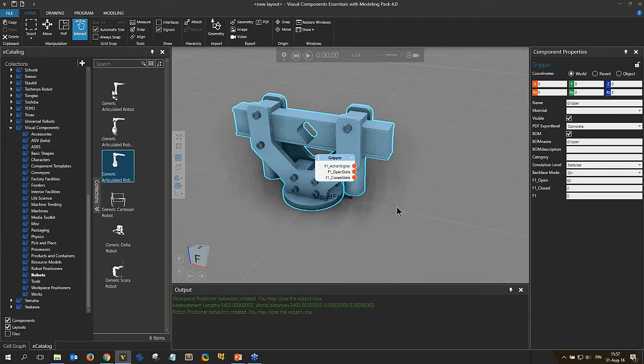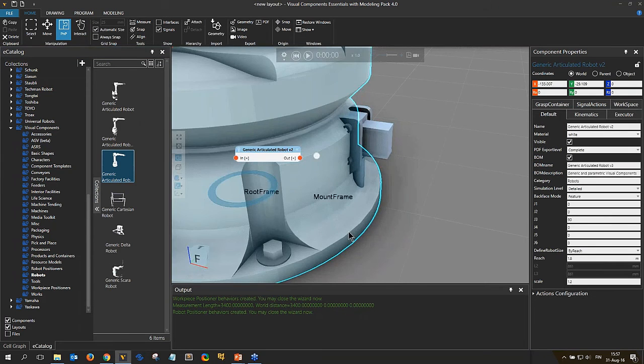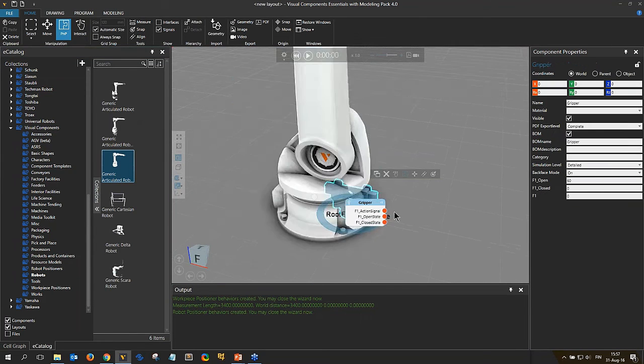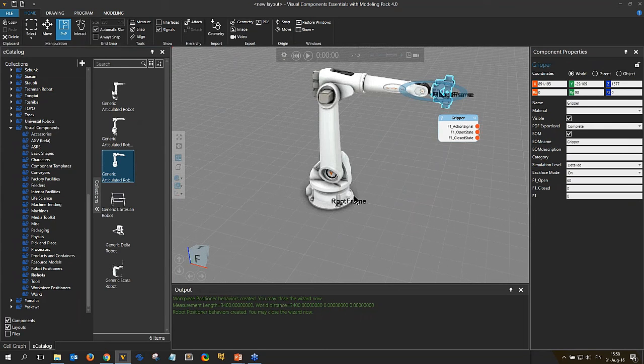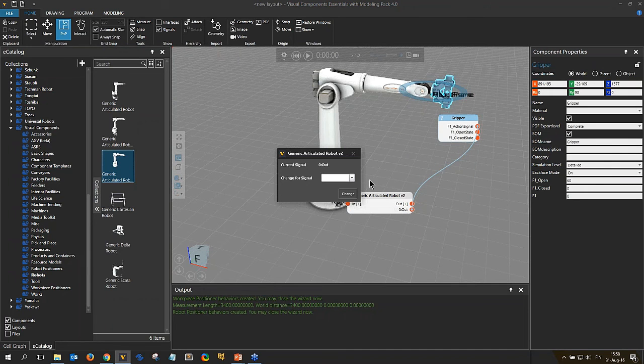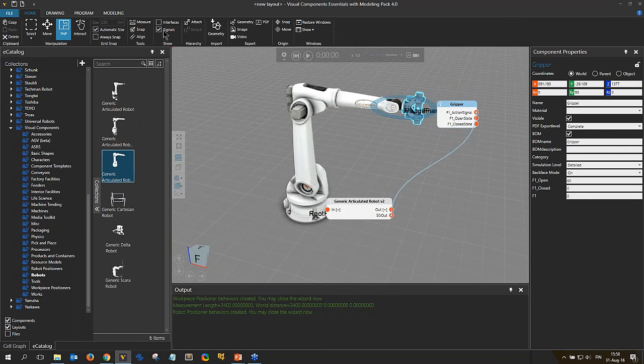So then we can actually see this guy in action. But now we can simply just double check that it connects correctly. Yep, and we can connect, for example, the action signal output to output 50. And now if we would fire from robot this to false, this would open. If we fire true, it would close. Quite straightforward. That's about gripper.